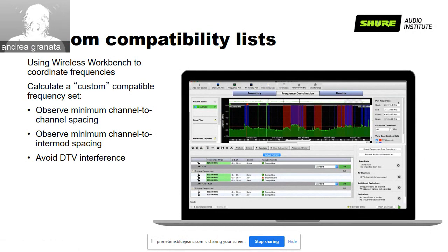It's just that what they want to achieve is to reduce the number of devices that, especially during takeoff and landing, are trying continuously to connect to the repeaters. So in theory, yes, a lot of mobile phones can create problems even in the UHF TV range. That is what we typically use to run wireless microphones. But this does not mean that we have a strong interference or disruption. It means that we may find a higher noise floor, especially in the top 100 megahertz of our spectrum. And there is not much we can do about it. It's just a little more RF noise that we have to deal with.